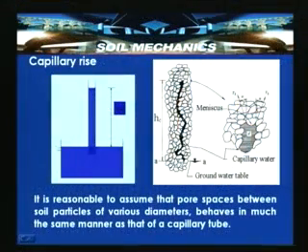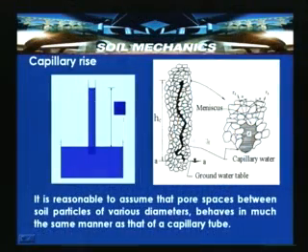So, let us look into how this works. This is the groundwater table, the free water surface, which is the level AA, and this is the diameter of the tube, which represents the pore space size. D may be the pore size, and then this is the rise. HC is the rise which is obtained here. Now you can see the menisci form at the top surface.